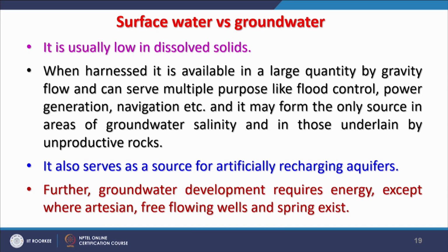So, if we recharge the groundwater regime in an area during monsoon time or through some surface structures, then our groundwater will be available sufficiently round the year. So, that is the best solution. Groundwater development of course requires energy, even to withdraw water from a groundwater well you require energy.